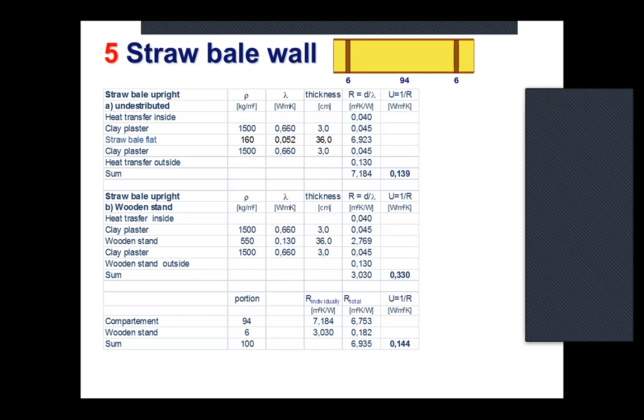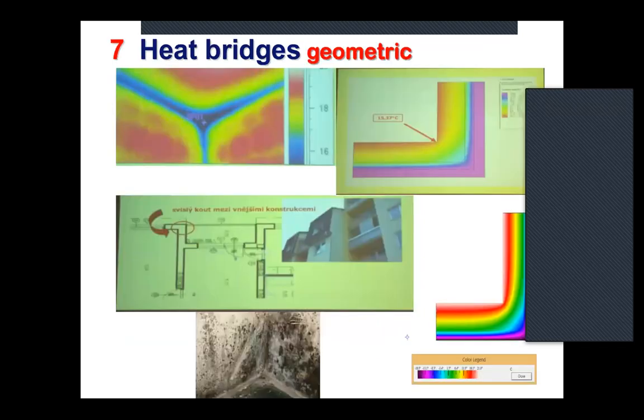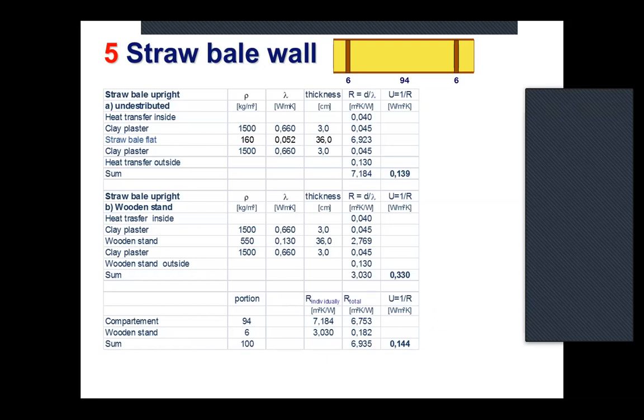Yeah, so for us, it's enough to know this, because these more complicated calculations are not necessary. Anyway, when you calculate the U value by hand, where you want to know the thickness of insulation you want to add, or the thickness of insulation you need, you should always have some reserve.